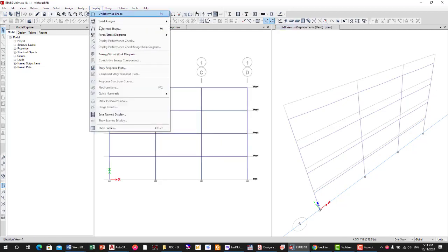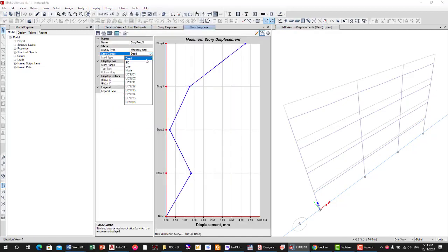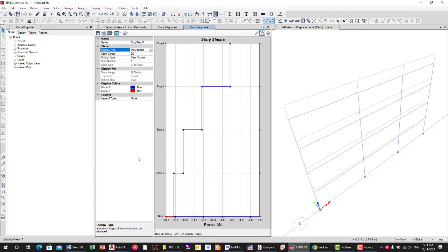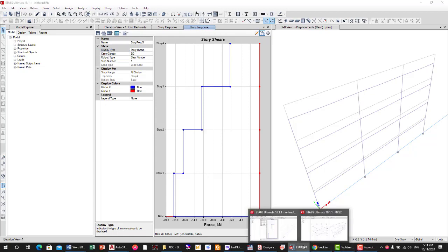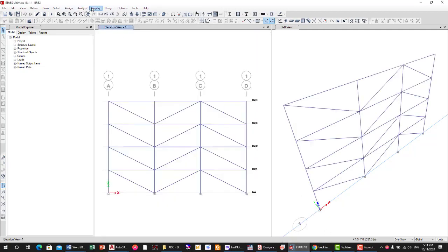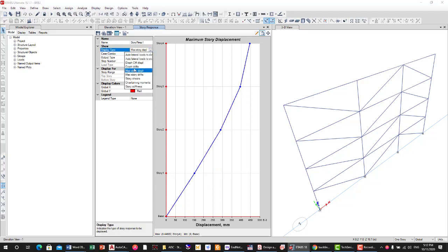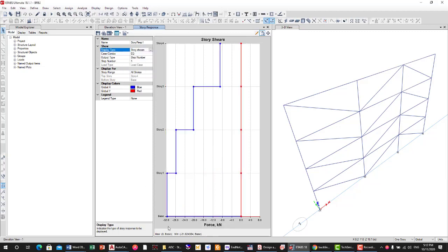Now let's see the response of shear force. Going to EQ and going to story shears. Now it's increased to about double because we reduced the R. So it's 18. Now we are going to see the other one, so it's about 31. So this system increased the shear force.